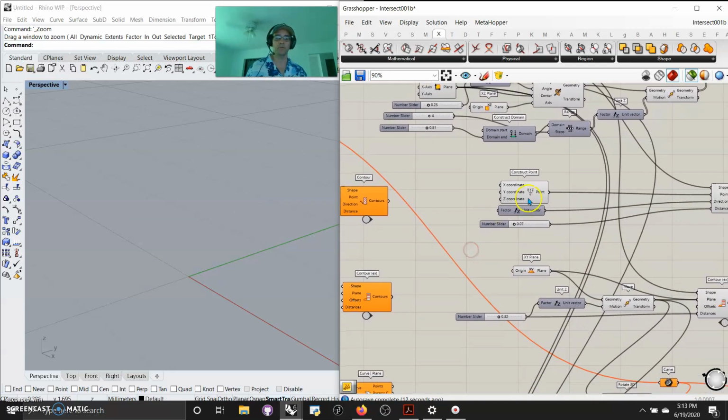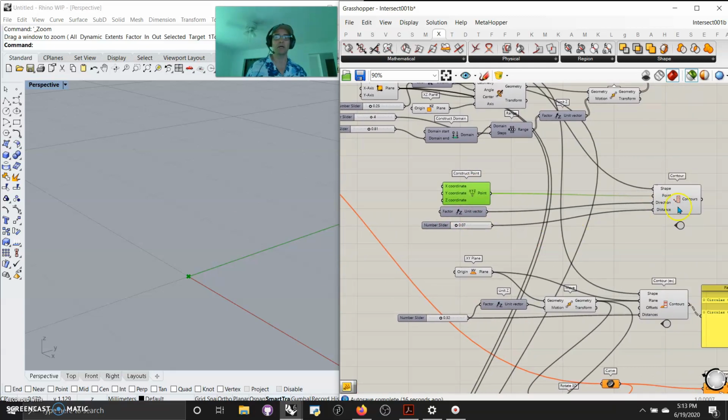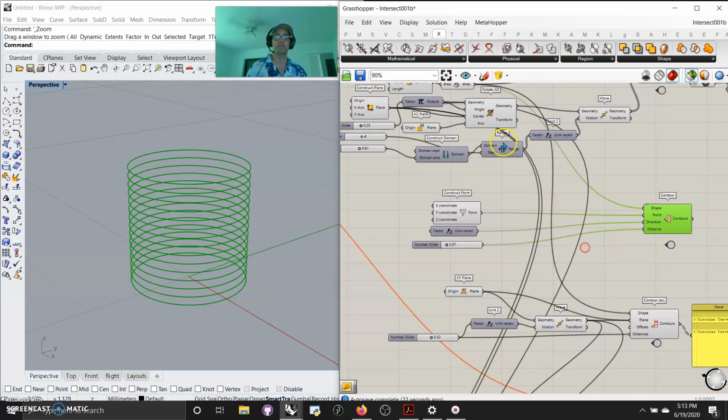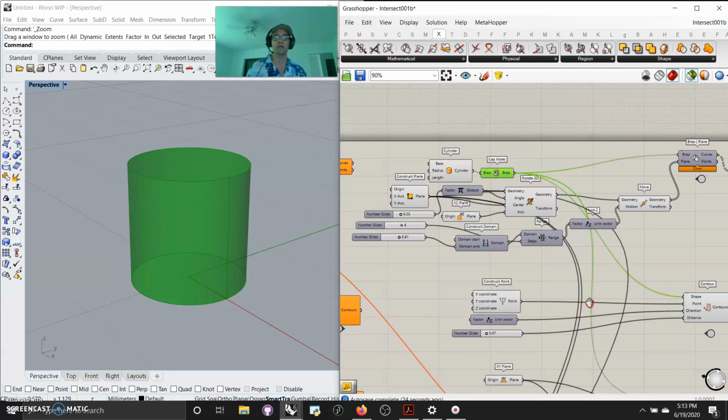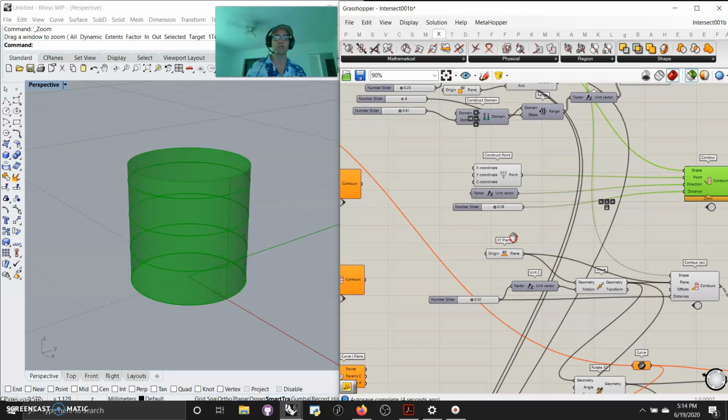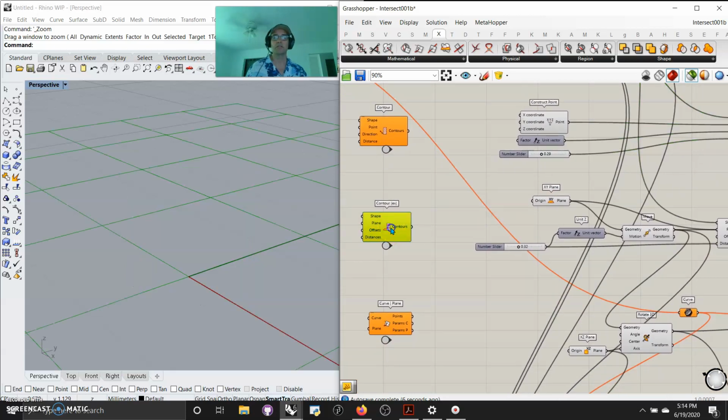Contour, well, that's pretty familiar for any fabricator. Take a point, which generates a point that you will then use to set the distance for contouring that piece of geometry. It turns out it's the same boundary representation of that cylinder. So if I want to grab that cylinder along with these lines, I can set the distance between them and contour any way I want in order to go to fabrication. Nice and easy. Let's go down to contour extended.